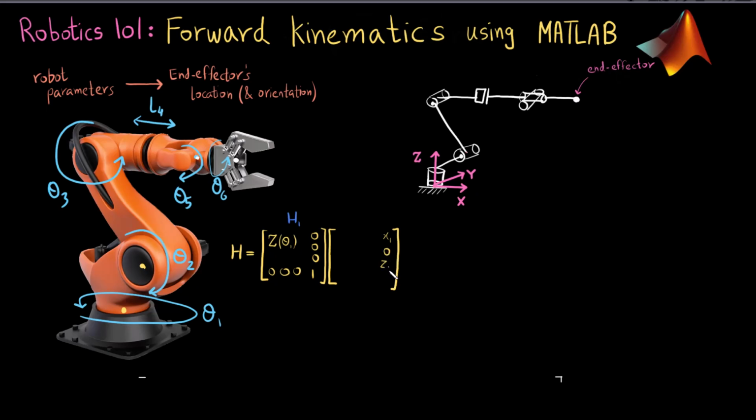And my last row is always 3 zeros and 1. Remember that if you have a real robot, these x1 and z1 are going to be fixed parameters, so they are known. When I do the coding for this, I'm just going to assume values for x1 and z1. So now this takes this point right here and translates it to this point.